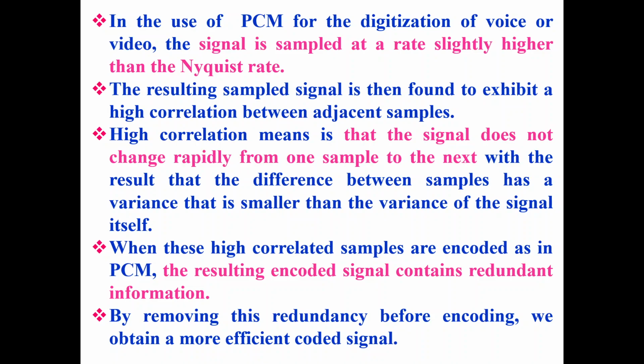We have started the digital modulation techniques with so many modulations. PCM is the base of your other modulation techniques. In PCM, the signals are sampled at a rate which is slightly higher than the Nyquist rate. This is nothing but your sampling theorem.